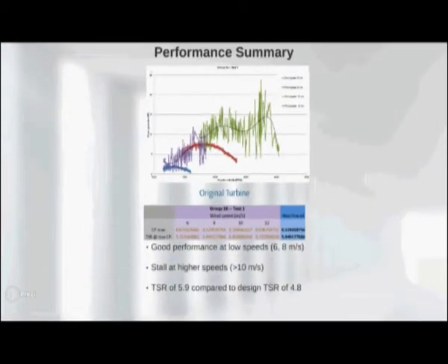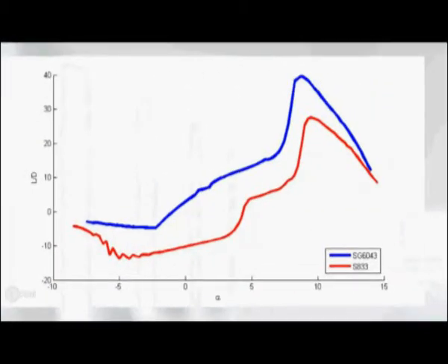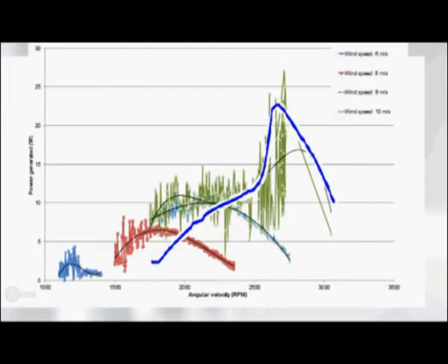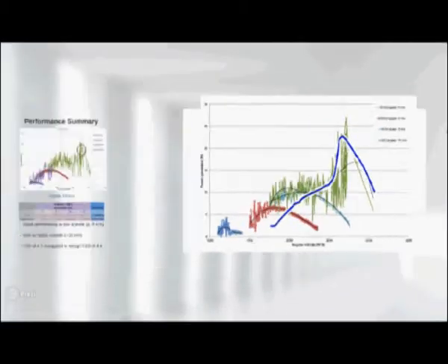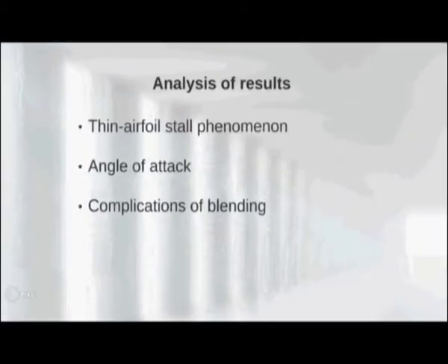Therefore, to maximize power, we had to twist the blade in accordance to the alpha L/D max of the airfoil section facing the local velocity. In doing so, coupled with the nature of the main airfoil section, SG6043, having a sharp lift-drag curve, this caused a large performance drop-off away from the optimum RPM, thus explaining the power spikes we saw on the power RPM graph. The limited range of performance is also reflected in quite aggressive stall cycle behavior beyond this range.